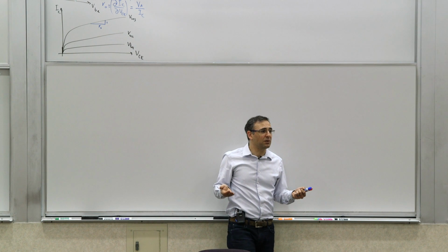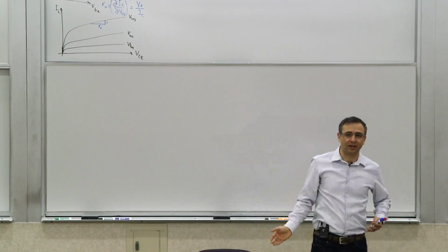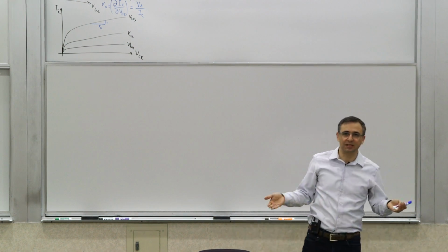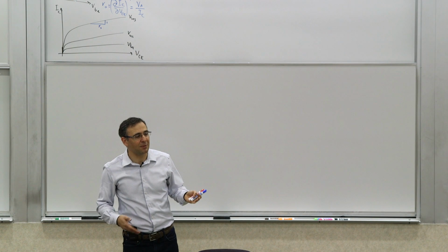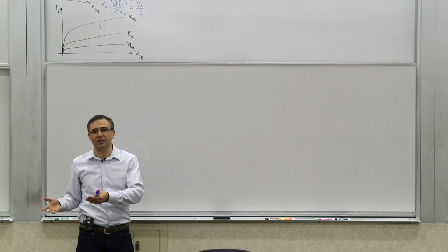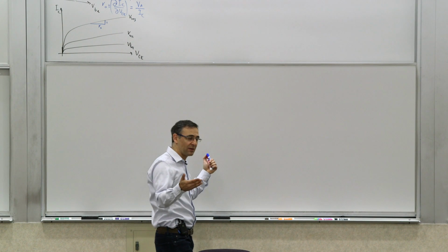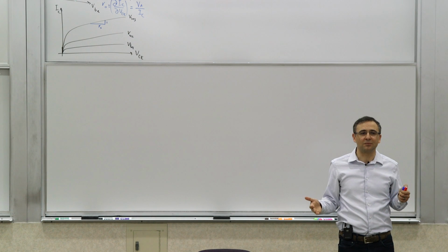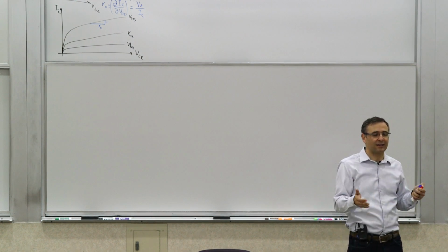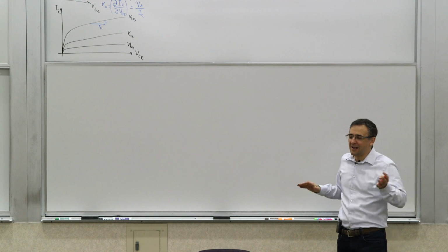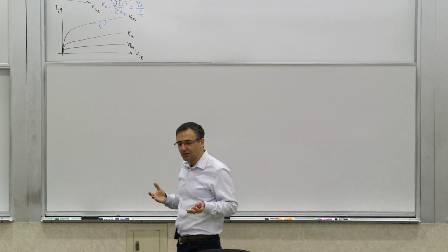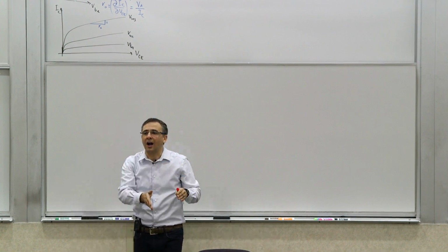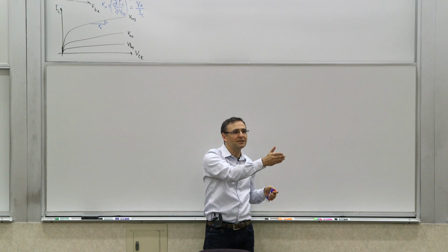Now, there are different kinds of amplifier. You can have voltage amplifiers, current amplifiers, trans-resistance amplifiers, or more generally trans-impedance amplifiers, or trans-conductance amplifiers, depending on the choice of the input and output, whether it's a current or voltage. And we said this, and we will repeat this. It's really a question of what the input and output impedances are. Whether something is classified as a voltage amplifier or a current amplifier is somewhat of an abstraction that can be helpful to think about, but really there is no dividing line. It's a continuum of the input and output impedances.